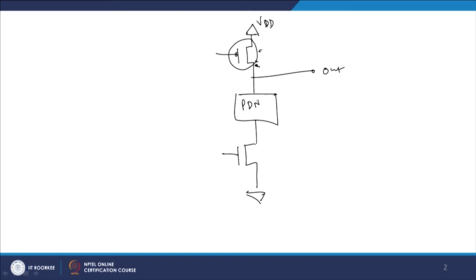So, if you look very carefully, if the clock goes high, right, ideally if the clock is not going high, it is typically at low stage or it is relatively low. So, let us suppose something happens here. If there is a capacitive coupling between this point and this point here, the voltage here will also shoot up, right. And as a result, there might be a scenario where this p plus n region gets forward biased, and this is quite dangerous in terms of operation.